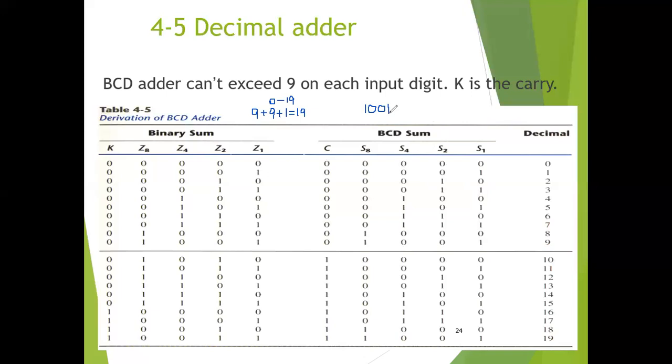As we can see here in this binary sum, these will be the invalid BCD representations. So an addition of binary number 6 to the binary sum will convert it to the correct BCD representation and will also produce an output carry as required for our operation.